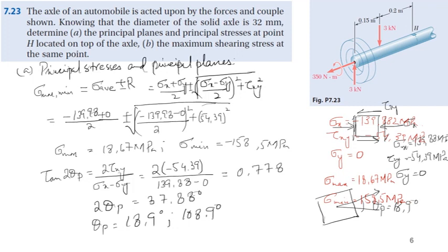So these are the principal planes, and we have principal stresses on those planes. If I want to write, we have compressive stresses of minus 158.5 megapascal, and on this face we have the maximum tensile stress, sorry, that will be minimum, 18.67 megapascal.